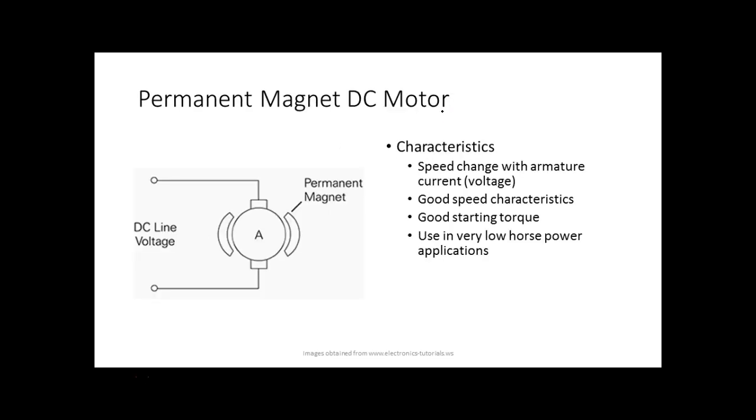And then we look at a permanent magnet motor. This is what you got on your car. Here you only got one option, is to control the speed by controlling the voltage you put on the armature. So the more voltage you put across the armature, it goes up, which causes the current to go up, which means the motor would try to create more torque. Well, what it would do is if it creates more torque, it's going to do what? It's going to run faster.